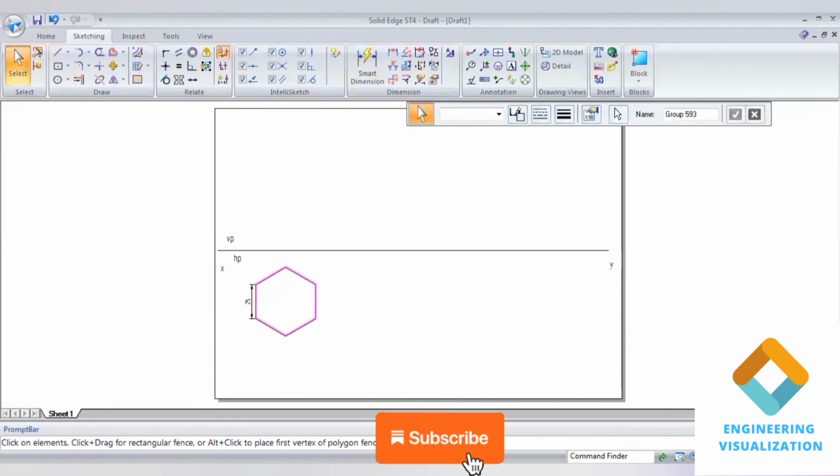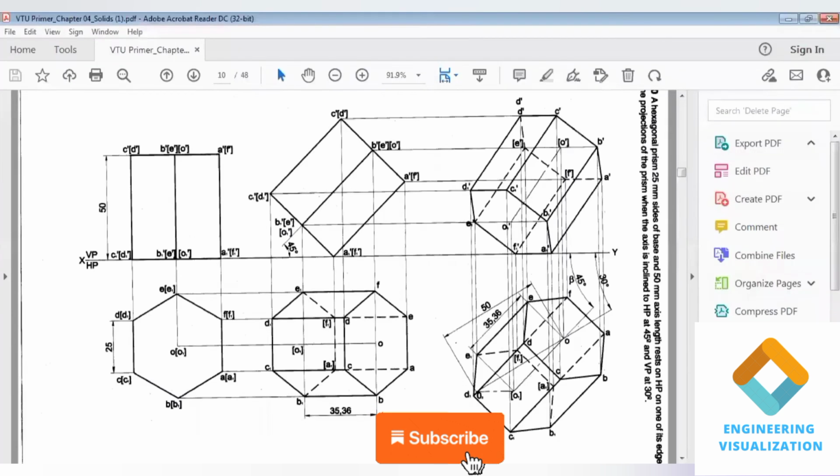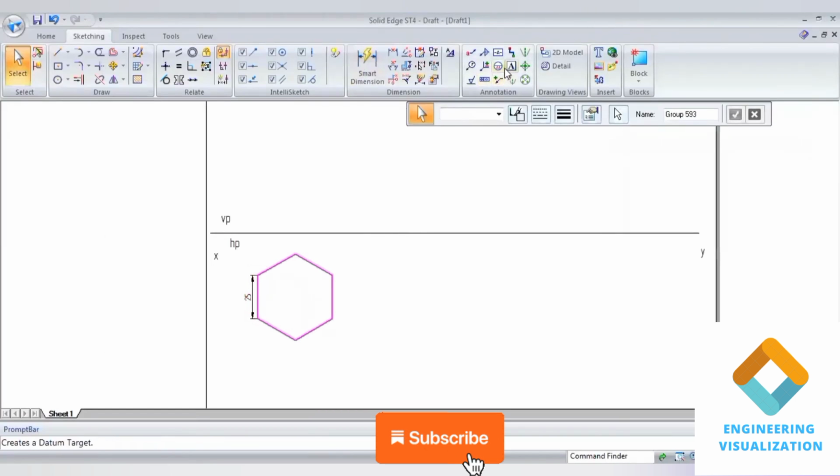Now write the notations for the top view and bottom view. Top view notations are written with A, B, C, D and bottom face notations are written A1, B1, C1 like that, but they should be written within brackets.